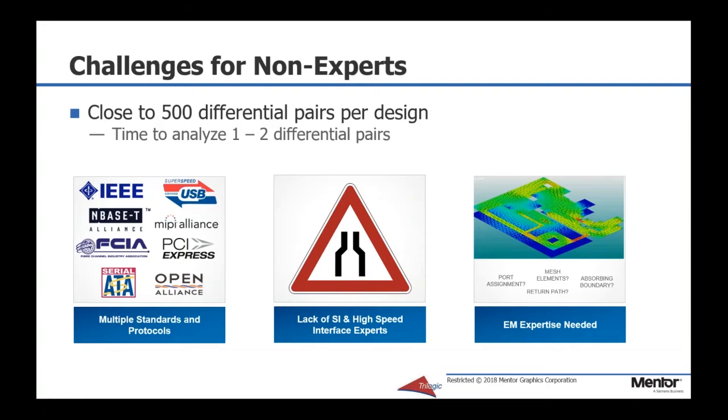Second, AMI buffer models, which are typically used for greater than 5 gigabit per second channels, are not easily available. Further, the buffer models are written for EDA specifications that are not ratified by the IBIS committee, so they generate different simulation results in different EDA tools. Which one is correct?